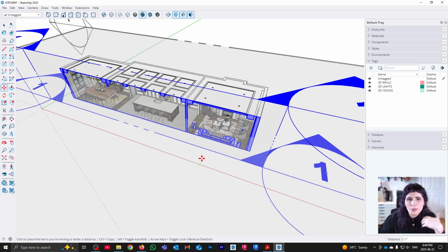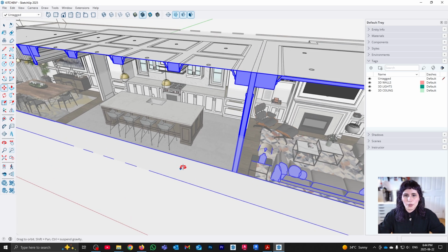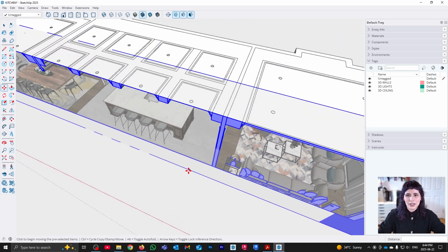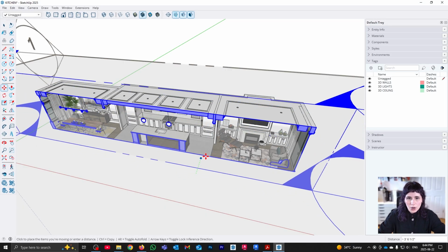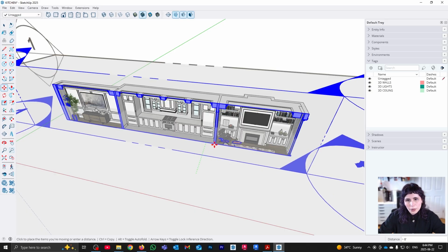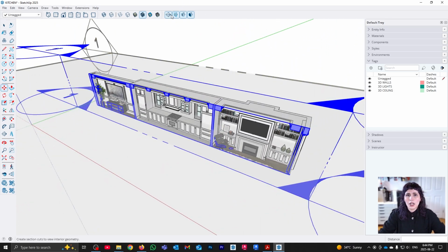This is another important thing. You get to decide where your sections stop, especially when it comes to elevation. So for example, for a kitchen design like this, you may want to have multiple elevations that are looking at the same direction. Maybe I want to have one where I'm just looking at the cabinetry that is against my wall, and then another elevation that is just looking at the island, right? So let's say that this one is going to be the one that looks just at my cabinets against my wall. Let's actually move it a bit more, so I'm cutting through the wall. There you go. That looks nice.